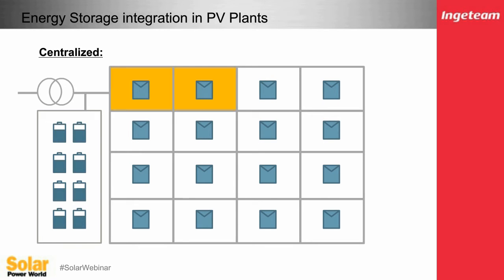With the centralized system, because it has a larger area, and if you remember back to the previous slide, you see less variation. In a large centralized system, you have a holistic plant of PV plus storage that takes advantage of the entire array having less variation, making your demand for DC battery sizing and design less demanding on your entire system.